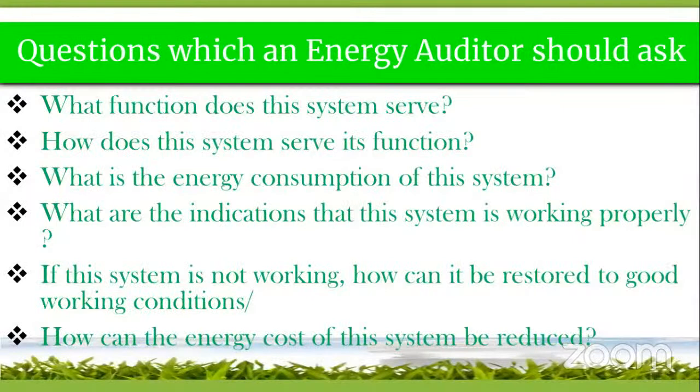The questions which an energy auditor should ask: What function does this system serve? How does this system serve its function? What is the energy consumption of this system? What are the indications that this system is working properly? If this system is not working, how can it be restored to good working condition? How can the energy cost of this system be reduced? Always we need to compare with the good benchmark and the cost factor. That's how the questions need to be.